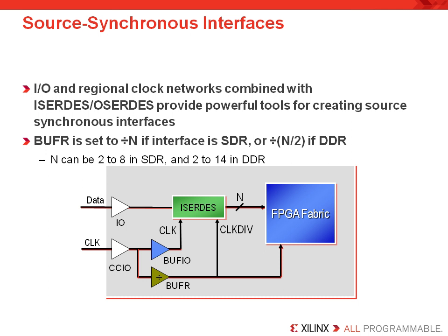In this example, we see a typical use of the SerDes resources. The BUFIO and the BUFR are placed in a clock region and have the same driver, the clock-capable I/O pins. Now they are intended to be used together to create the 2 clocks, that's the high-speed and the low-speed clocks required for a SerDes component. This explains why the BUFR resources do clock division.